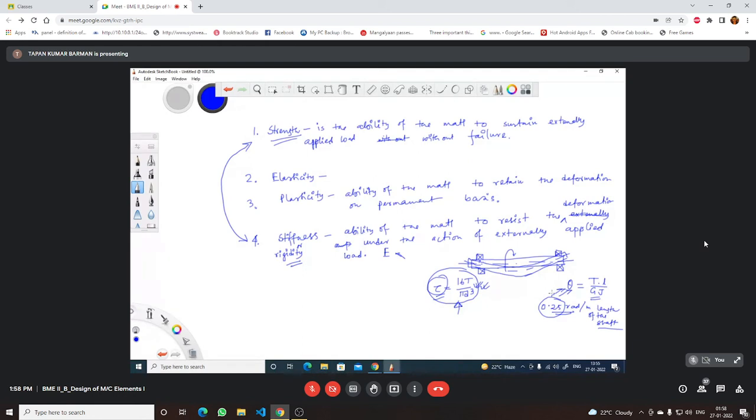Because here you see in the shaft, sometimes in addition to torque, there should be other loadings also. It may be bending loading or bending moment, maybe axial loading. So you have to combine those loadings to make the design. Also, sometimes we are considering the lateral or angular rigidity. Also, we will go for ASME code to make the design. Please wait for some time. Definitely we will demonstrate the problems here in the classroom only.